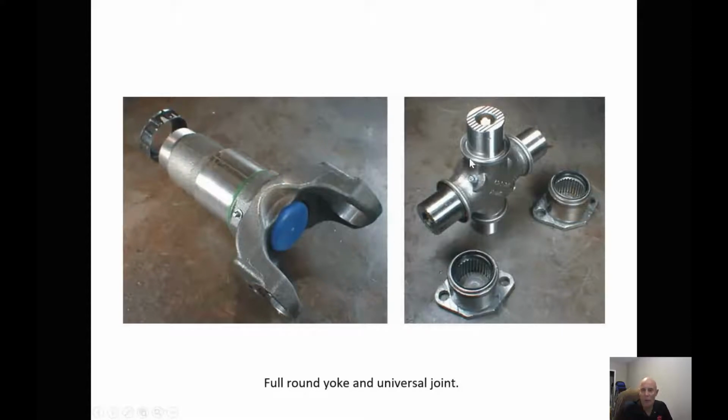The other thing to be aware of is these plastic caps inside. On a brand new one or a used one, if we're taking a used one apart, sometimes these white plastic plugs stay inside here. So we want to make sure that each one of these 4 has it, and that'll help ensure that grease gets distributed evenly throughout the 4. The other thing is making sure all our needles and our seal stay in place.